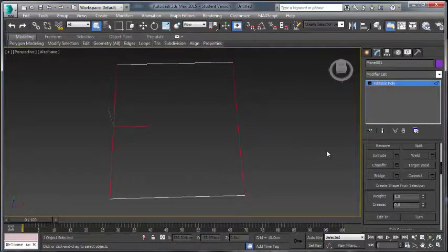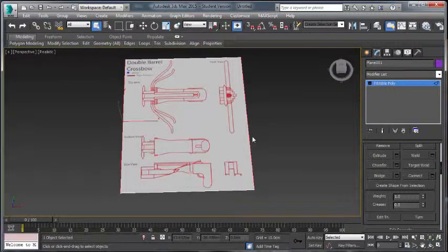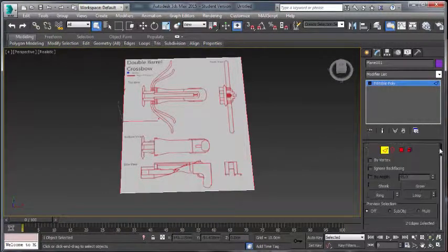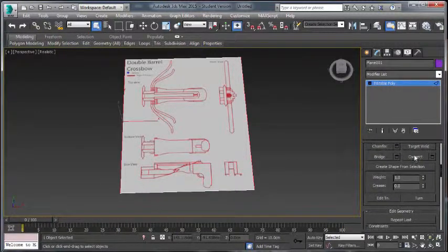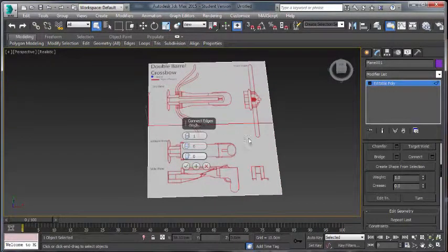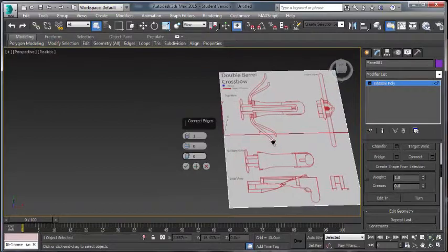So I'll go back out of F3 and back into the modifier tab, back into the selection tab I should say. Select the little connect tool, but we don't want to press the button. We want to press the little grey, the black box that's the connection settings. If we click on that, a little dialog box appears up here.